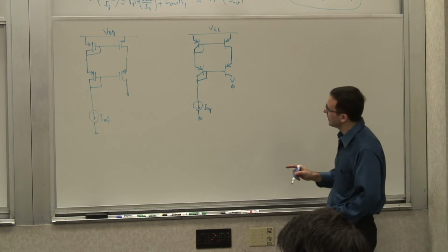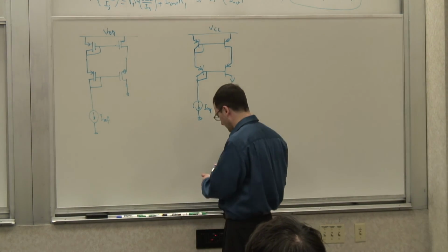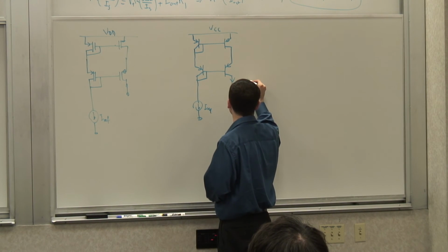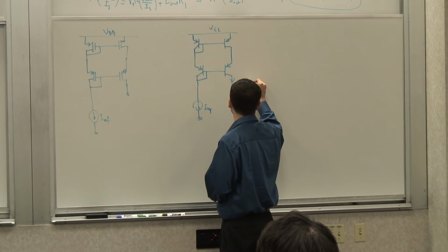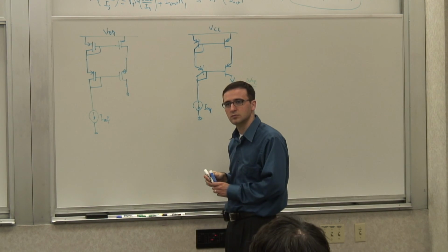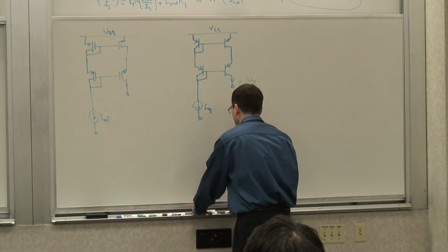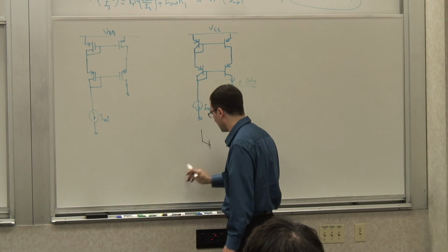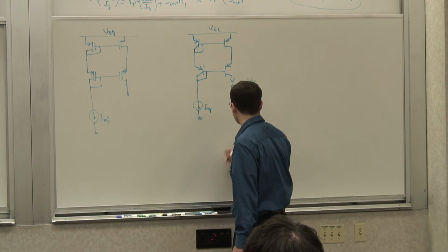Now, interestingly, if you look at this, we saw that the output resistance of this guy was beta r over 2. Of course, it would be beta of the PNP, r of the PNP over 2. But still, using the higher output resistance. Now, the interesting thing is that there's a variation of this kind of current source. So this is the NPN version of that.